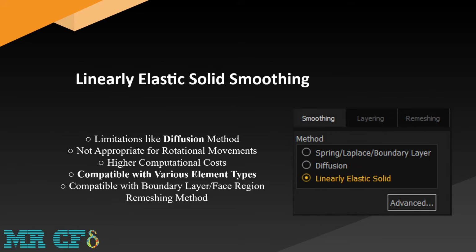In addition, the linear elastic solid smoothing method is incompatible with the boundary layer smoothing method or the phase region remeshing method. That is, it is recommended not to use these mesh update methods at the same time when using the linear elastic solid smoothing method.